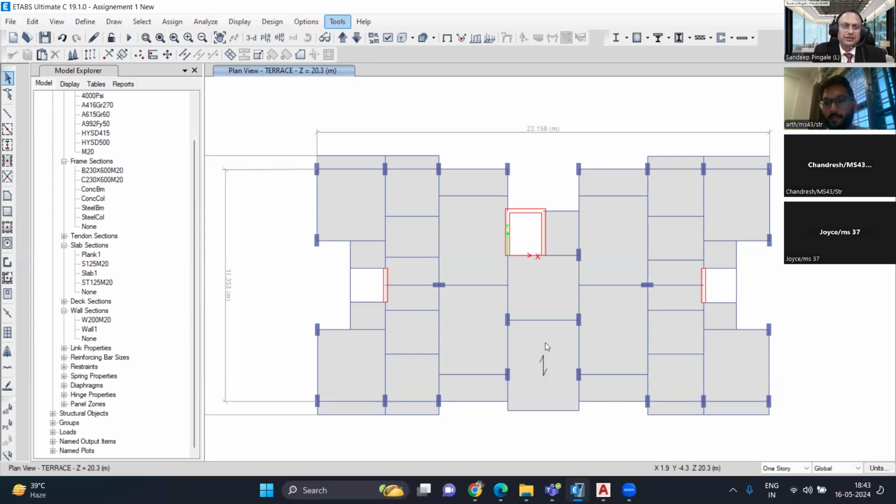Yes, sir. Understood. If you go to the advanced areas, once the basic modal analysis is perfect, releases are there, you're given the stiffness, the dead load, the earthquake load, the dynamic, static, dynamic scale factor, these things are done. Then you check the modal shapes, because modal analysis is the behavioral understanding. Some model is done, sir. Once it is done, then you go to the next one, the advanced part.